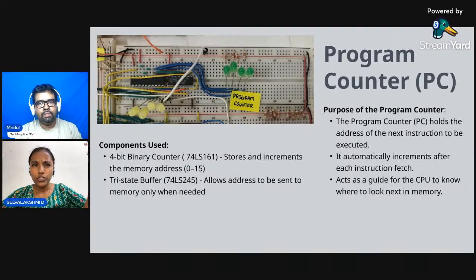And the output goes to MAR via 74LS245. It is a bus transceiver. And for the complete project, we are using the 74LS series. And this transceiver helps us to output the program counter data to the bus.